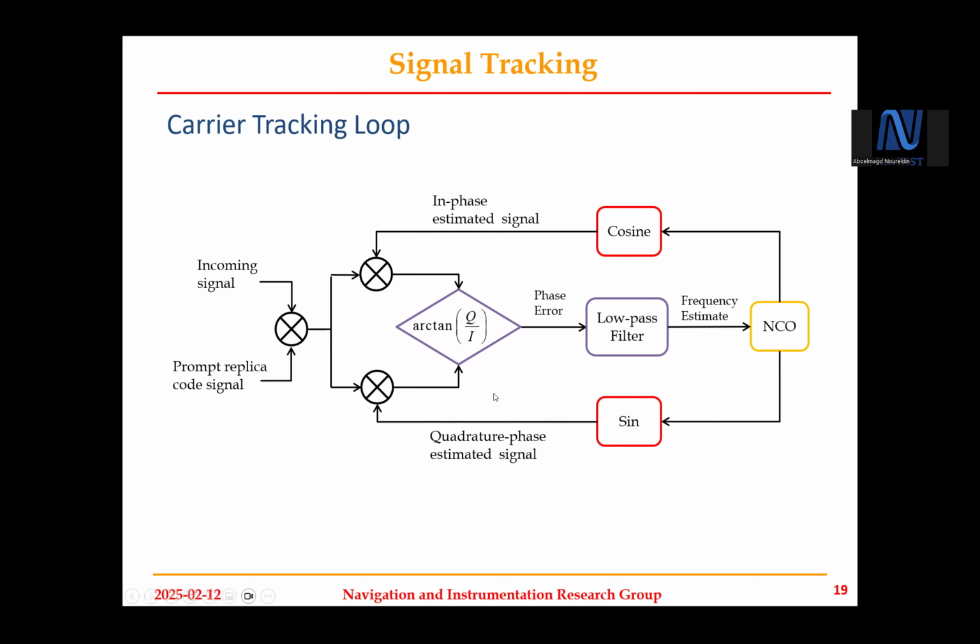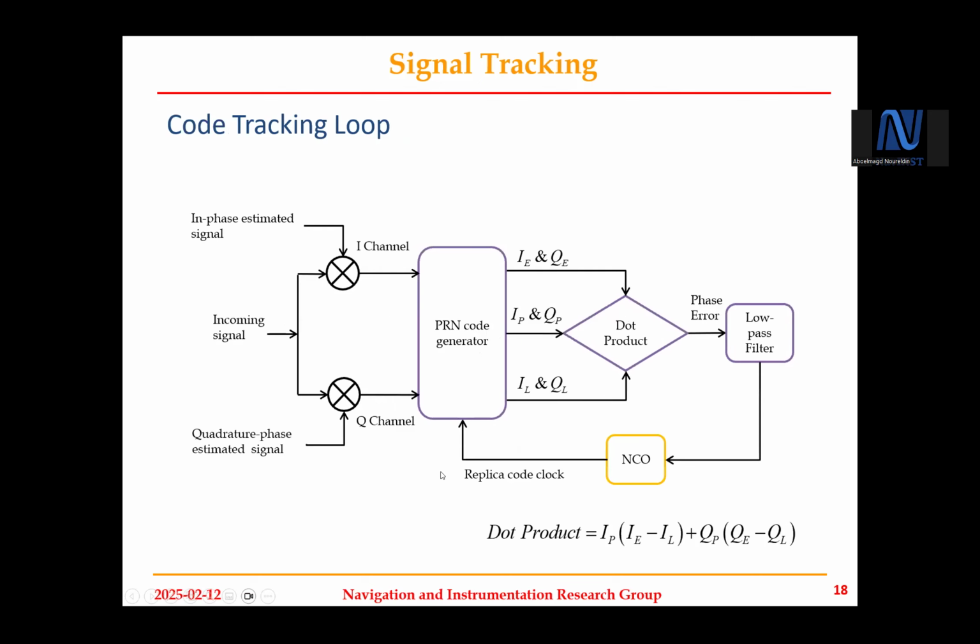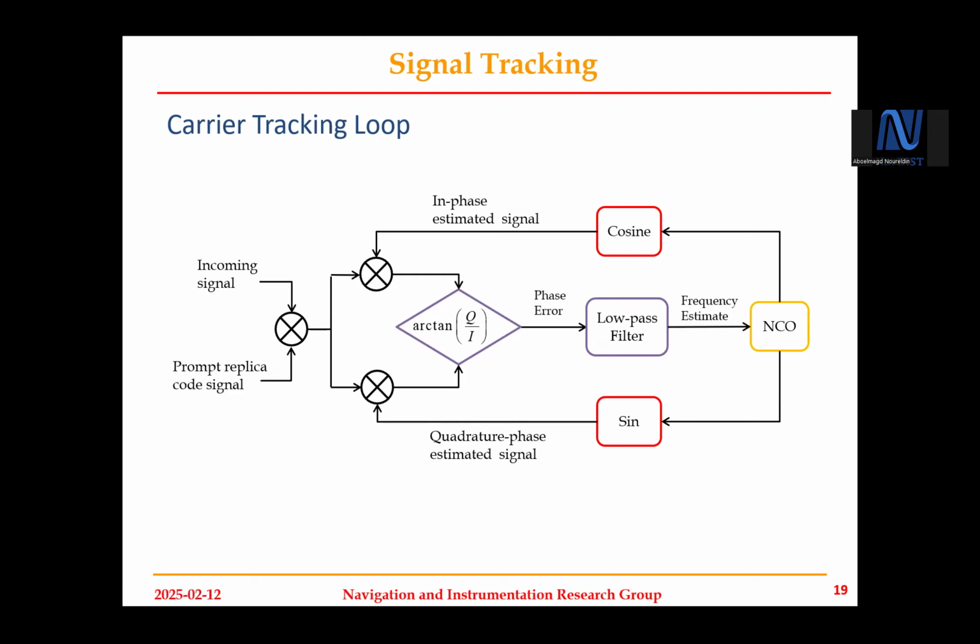With this cycle, those two blocks cooperate concurrently, so we keep track of both parameters of interest: the code phase, which eventually represents the delay on the signal, and the frequency, which represents the Doppler on the signal, so we can adjust ourselves in both search directions.